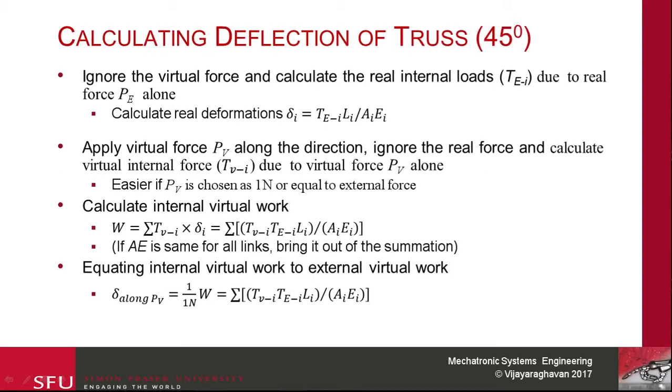What we're going to do is ignore the virtual force and calculate the real internal loads T_e,i due to the real external force P. Then we can calculate the deflection or the deformation using this formula over here. Once that happens, we apply just the virtual force and ignore the real force, and then calculate the internal virtual forces T_v,i due to the virtual force P_V, which is 1 Newton, along the direction in which we want to find the deformation.